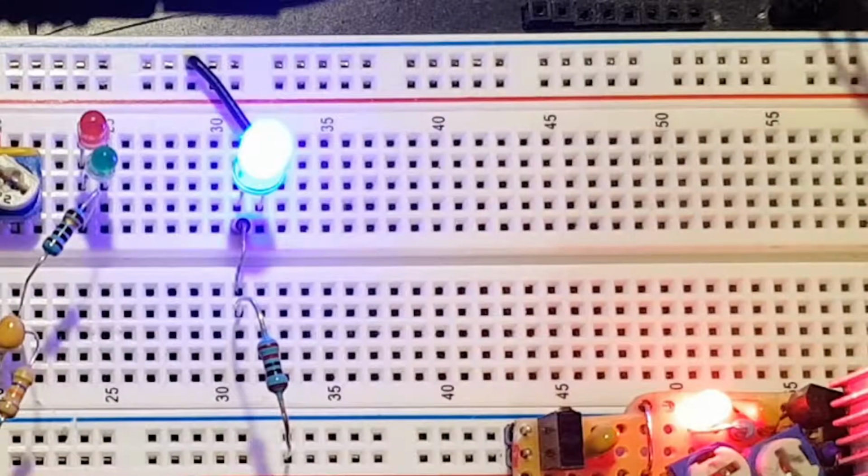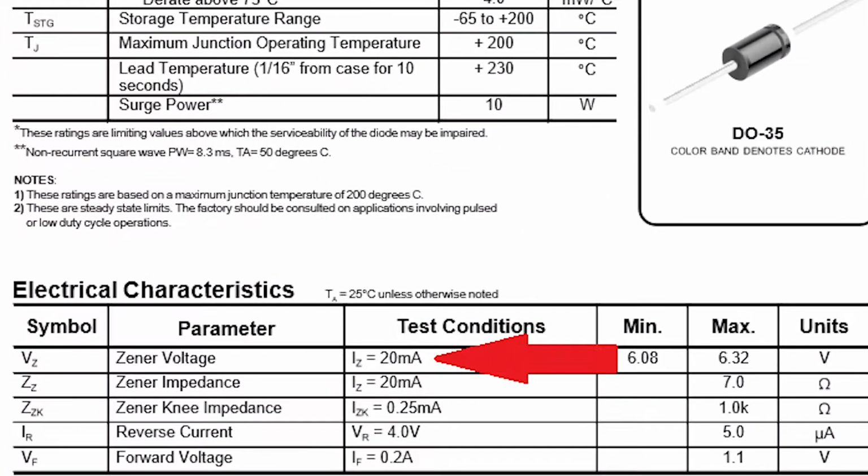Any diode will conduct in the wrong direction once this breakdown voltage is reached. This is called reverse bias. This will invariably lead to the diode becoming damaged and of course probably your circuit too. Zener diodes are actually designed to be able to conduct in reverse bias at a specific voltage. This is a 5.5 volt Zener, so will conduct in reverse bias once 5.5 volts is reached. They're designed to break down with more control, so they will limit the reverse bias voltage to the Zener voltage.